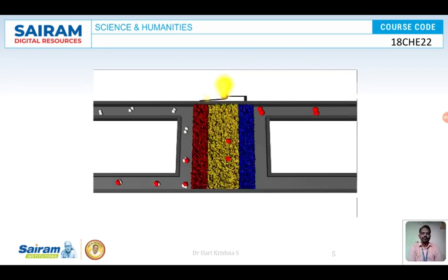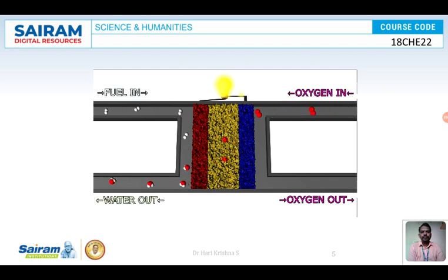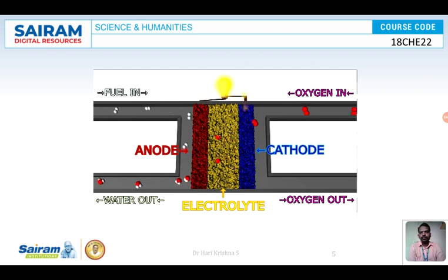A solid oxide fuel cell is an electrochemical device that produces electrical energy by oxidizing fuel. This system consists of a porous anode and cathode that are separated by an ion-conductive solid electrolyte. In this device, the fuel is oxidized at the anode, while the reduction of oxygen takes place at the cathode. These reactions are possible if the electrons participating in this process can move from the anode to the cathode, but the only way to do that is to use an outer circuit. And that's where we can harness the electrical energy.